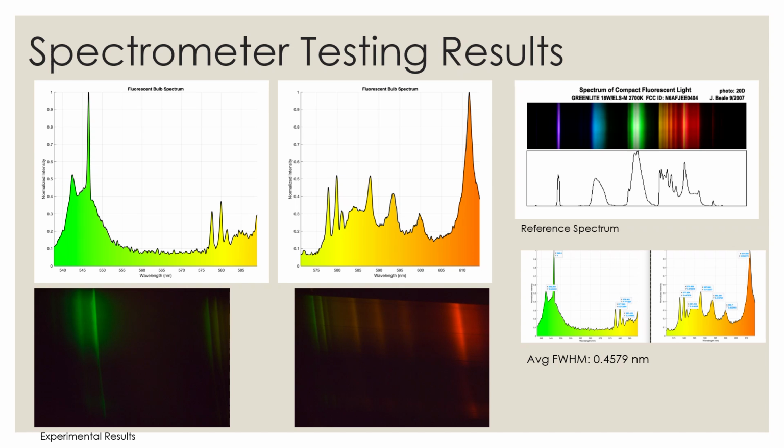This resulted in a 0.46 nanometer full width at half max, which is within our spectrometer's resolution requirement. We know our spectral range requirement is met. This process establishes our calibration approach for integrating the spectrometer with the CCD in its final housing. The next steps include refining the spectrometer's alignment, integrating with the CCD, and coupling with the probe optics.